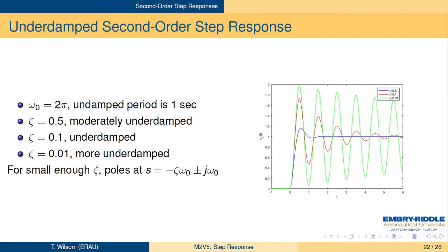You might do it on the homework, but it's just good to have a sense of how you could look at a graph. Somebody comes in and says, I've measured this on the scope. How do I figure out what zeta and omega naught are? You say, oh, I can do that. I take the oscillation rate from the 0 crossings, or it's actually the crossing at the steady state value. If it's not really zeros there, it's 1, the steady state value that it's decaying to. And then I look at the decay from 1 peak to the next, or from 2 peaks or 3 peaks, and figure out what that rate of exponential decay is.